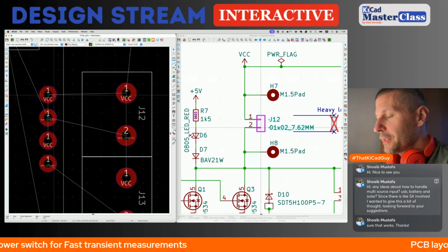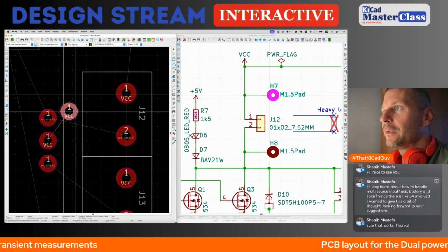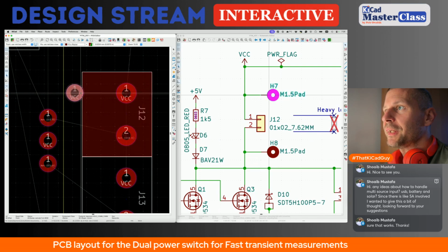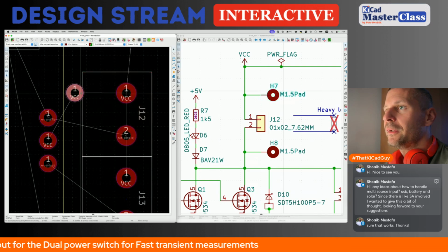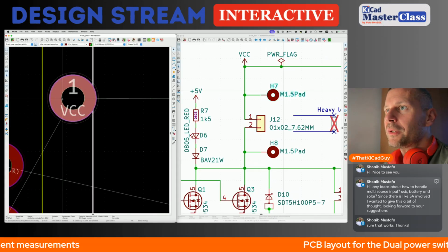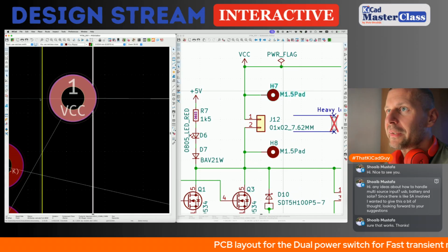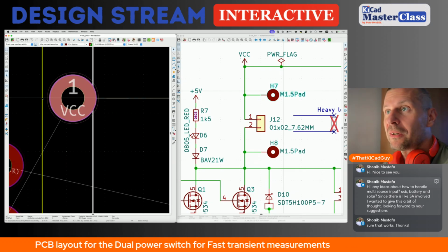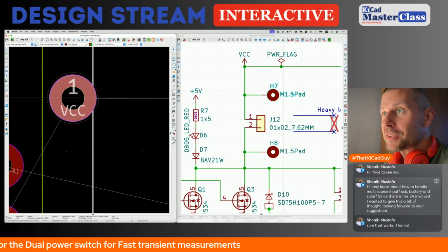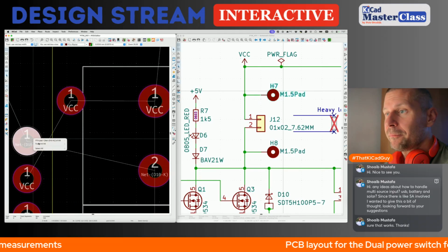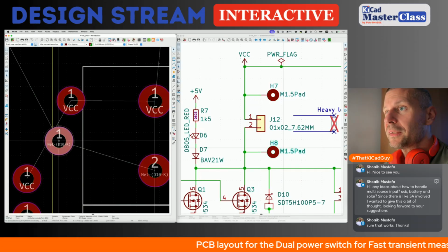I need to place these test points near the edge of the PCB. The reason is that I want to use the hook grips on the cables, and when the hook grip is close to the edge of the PCB, I don't need to use the soldering. I don't have to solder the wire. I just use the hook grip. Yes, and 1.27 is, I think, a good distance.